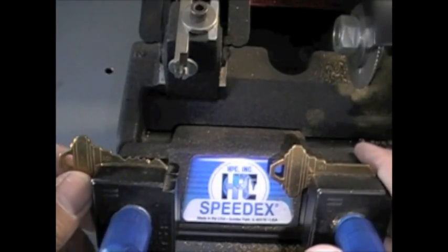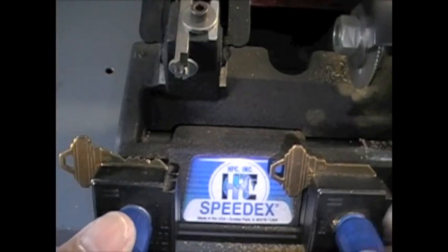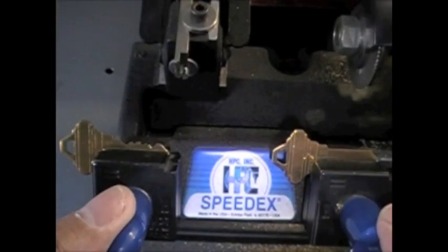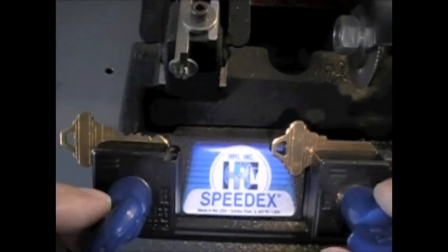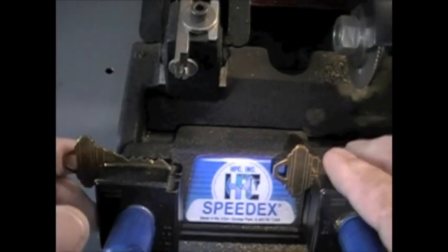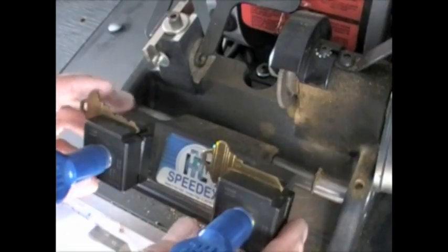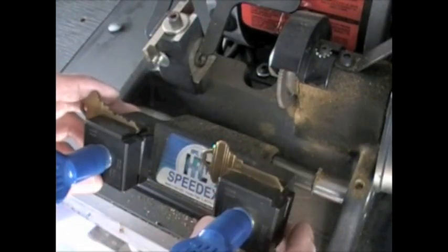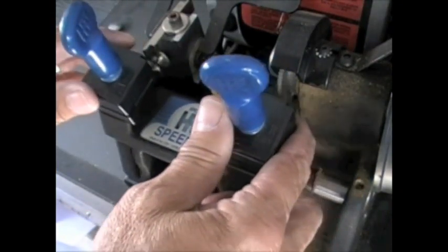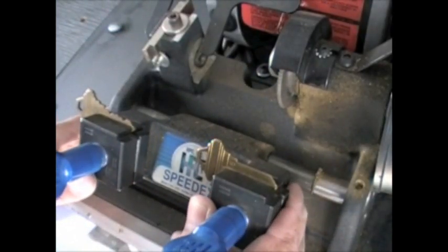Now when you get ready to cut, you want to make sure that your key gauge is flipped up out of the way. You want to make sure that both your original key and your key blank are in the jaws very snugly. Again, you don't have to overtighten, but they should be in there pretty firm. They're not going to be moving around. So check that before you start cutting. Okay, now I'm going to go ahead and cut this key, and I'm going to turn the machine on, and I'll bring up the key again, and I'll make about 3 passes to cut this key, and then we'll deburr it.